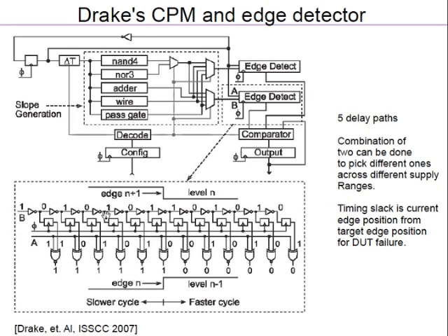So now you have these edges here, again the same concept. The edge comes in here and then it gets captured. That is not shown here, but it gets captured by these flops. It's like taking a snapshot. You take a snapshot and the output of the flops are essentially capturing the state of the nodes out here in the delay line gauge.